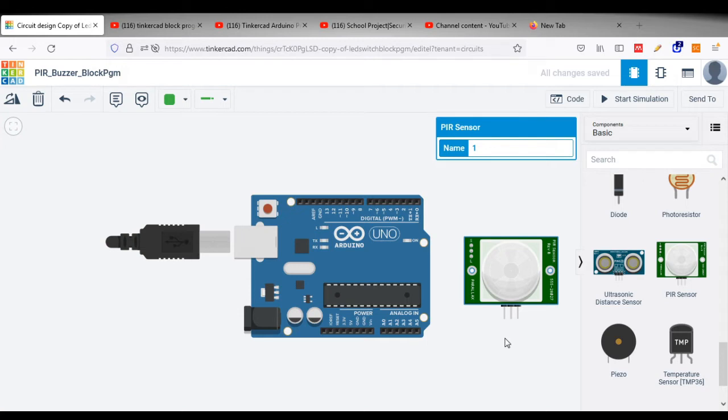It will detect the passive infrared rays emitted from a human body, that is heat radiation is emitted from the human body, and there is a Fresnel lens over the sensor. This white color thing is a Fresnel lens. So whatever heat radiations are coming and falling on the Fresnel lens will be converged to a particular sensor present inside, which is kept below the Fresnel lens, and when the infrared value is above a certain limit, it will be detected as motion.